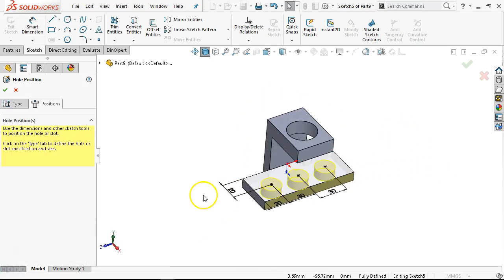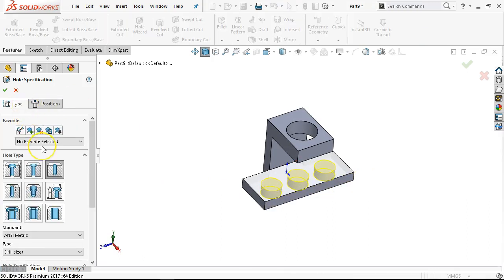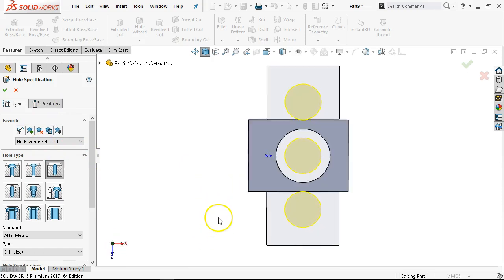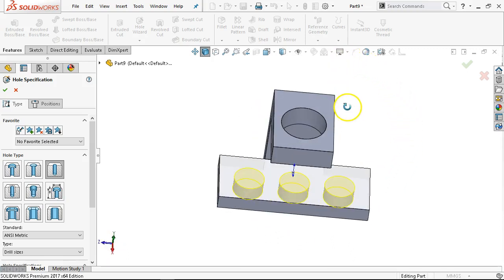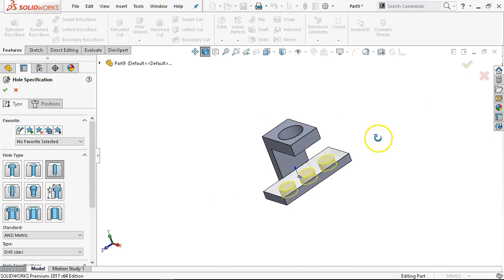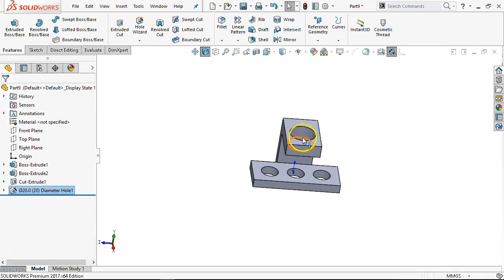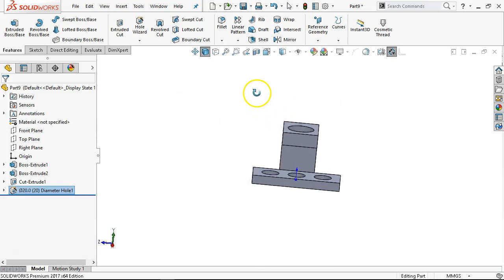All right, so again, the advantage of the, and let's see, is that one centered? That one might be. Yeah, we could probably, well, those are pretty close to the edge. So that would be a trick, machining it in one direction. I'm going to say the advantage is that if I wanted to change over to a counterbore or countersink, I can do that seamlessly. The top one, I would either have to generate the geometry or delete it and go back in with the Hole Wizard.